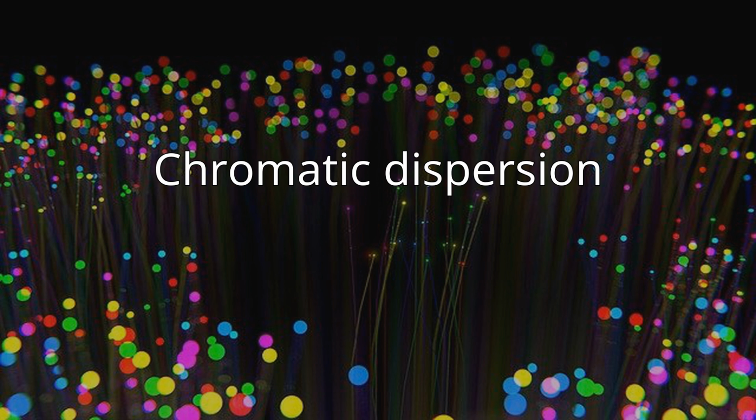Chromatic dispersion. The refractive index of fibers varies slightly with the frequency of light, and light sources are not perfectly monochromatic. Modulation of the light source to transmit a signal also slightly widens the frequency band of the transmitted light. This has the effect that, over long distances and at high modulation speeds, the different frequencies of light can take different times to arrive at the receiver, ultimately making the signal impossible to discern and requiring extra repeaters.